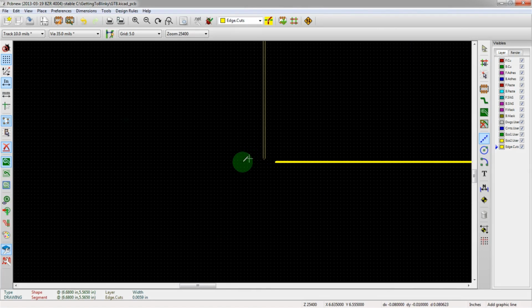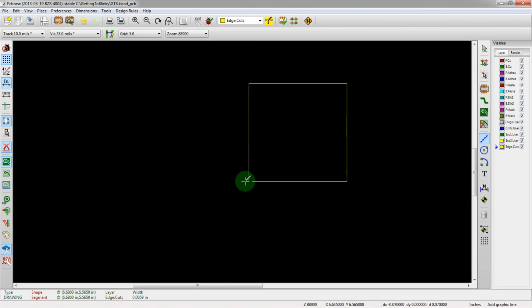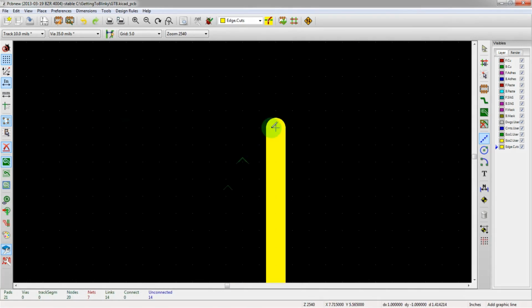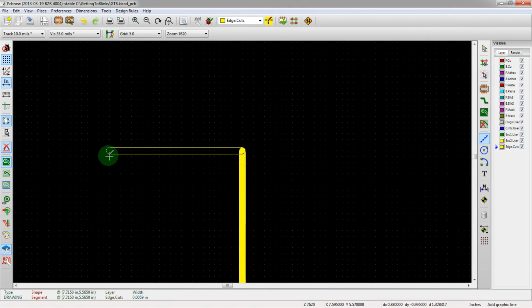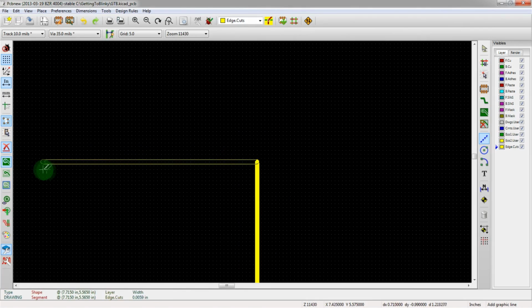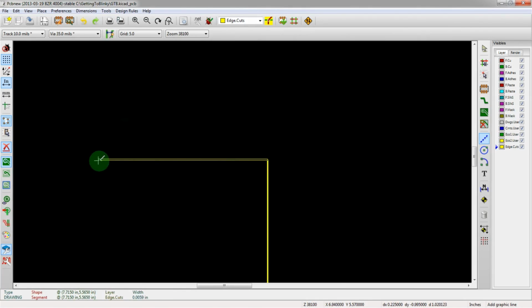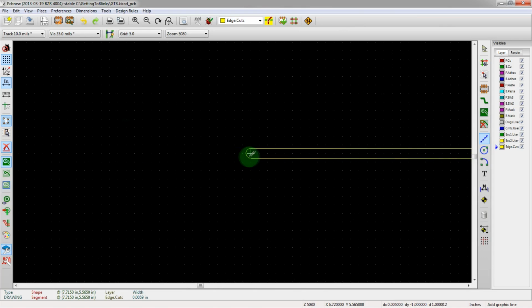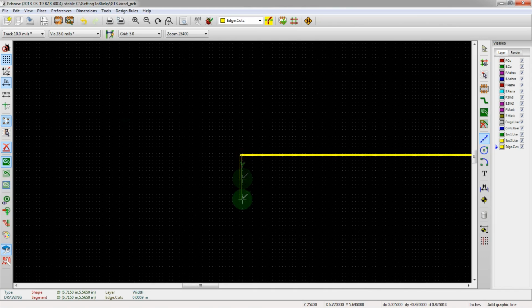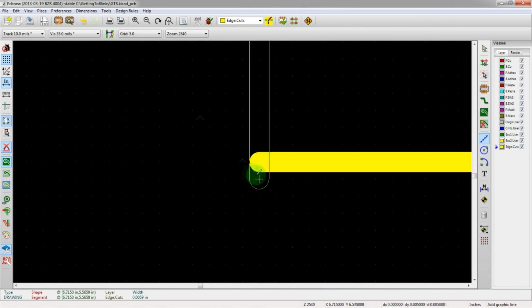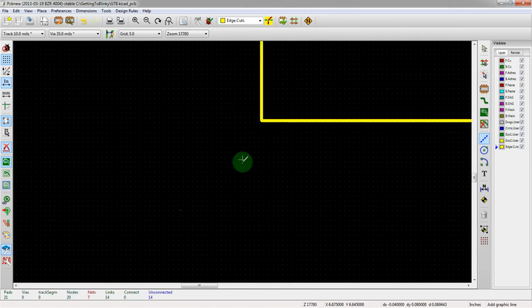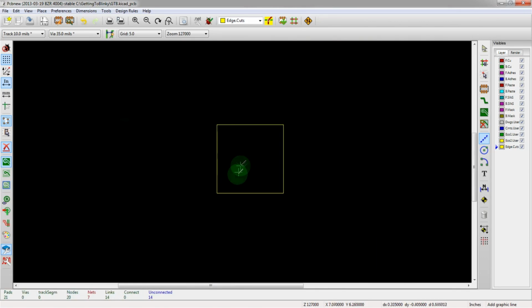And then, oh, no, I must have, shootski. Let's go back one, zoom in, click on the edge here. Huh. That's why. We're going back towards 0. I was thinking the other direction. We're actually going back towards 0 here. So you need to keep that mental math in your head. That should be good now. And then we go down back to 0, 0 in that differential area, the dx, dy. Double click, and we're good. Alright, so we have a board outline. Awesome. That's a good thing.